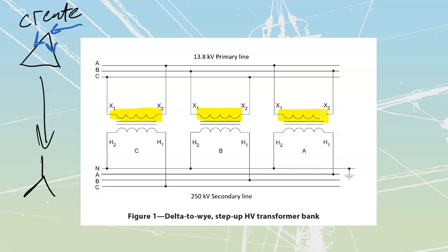It allows for a reduction in the cross-section area of the windings, so the winding copper. It also means that the windings are going to be closer together, which means that we are going to be able to get much better flux linkage. We're going to have less losses inside of there. And it means that our transformer is going to be able to be a bit smaller because we've got smaller windings that are going to be placed inside of here. We then transform through the magic of magnetic flux over to our high voltage Y side.